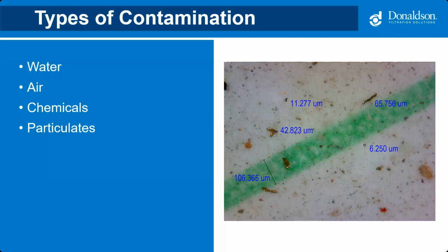Chemical contamination, if we just take a look at the oxidization cycle, if you've ever heard varnish being thrown around, something that looks like that kind of tainted plating out of varnish on components, that rapid oxidization essentially is allowing that to occur. That can cause stickiness in valves. It can plate out on all sorts of different things, cause valves to stick, and that piece of equipment may not move properly. It can also cause heat spots or hot spots on different components and cause them to wear out faster.